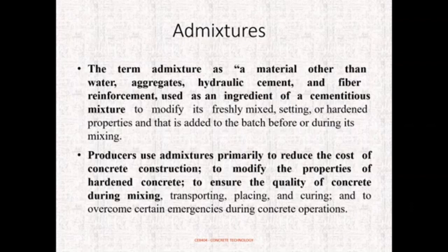Why do we use admixtures? Usually, admixtures are used to reduce the cost of the concrete, to modify the fresh and hardened properties of concrete, and it also ensures the quality of the concrete during mixing, transporting, placing, and curing, and also it overcomes certain emergencies during the concrete operations.